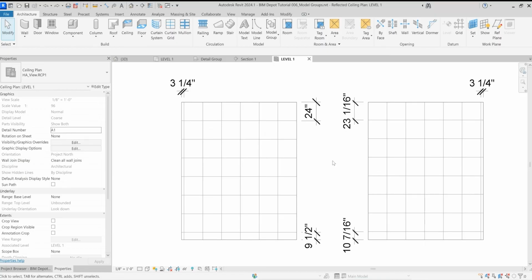Ways that I've dealt with this in the past, say if we do have a symmetrical space on a mirrored axis, I'll just leave the ceiling or whatever has that specific fill pattern out of the group. And then unfortunately, you just have to redo it, model them independently.